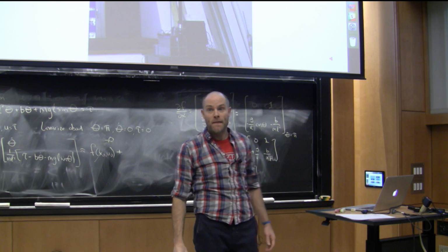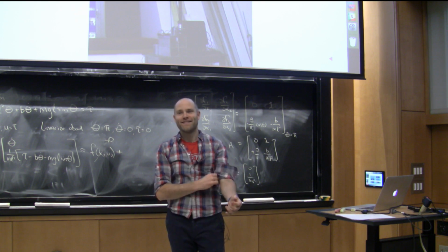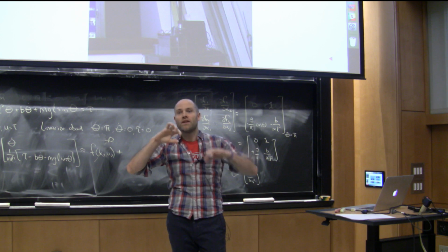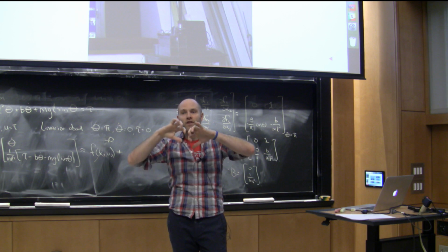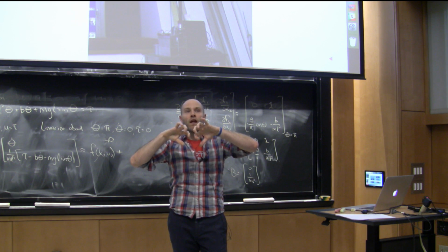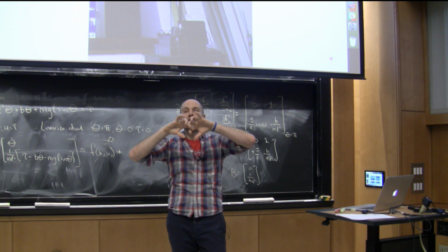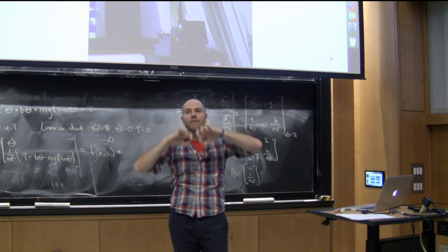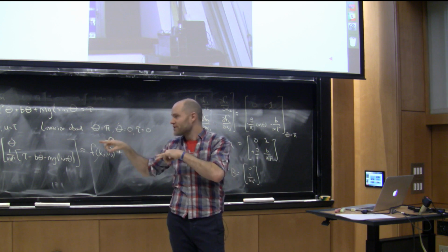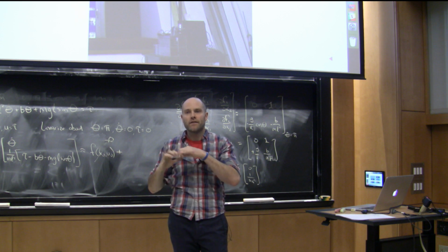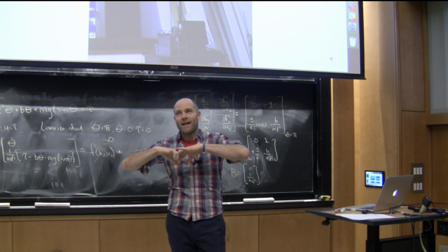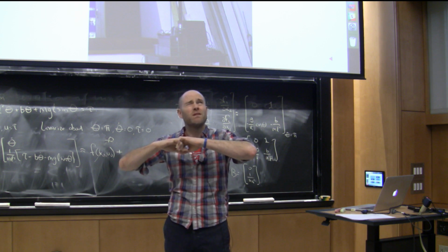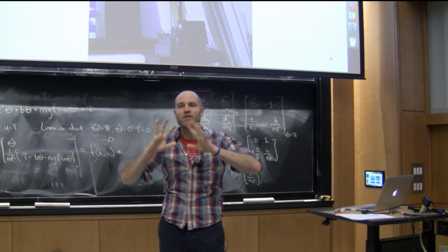Wait, why can't you put that into your equations of motion? You can, but it's hard. Because the effect is a discrete effect, right? So I would have the additional state of the transmission relative to my equations of motion, and I could write that. If it was just a ratio or something, I could definitely write that. But if the dynamics are, if this, then go in this direction, the equations are one way, if this, go in the other way, I now have a discontinuity in my vector field. My linearization tools don't go through that, and you need more powerful tools. And I actually would say it's still an open problem. I think that there's not great satisfying solutions to this problem.